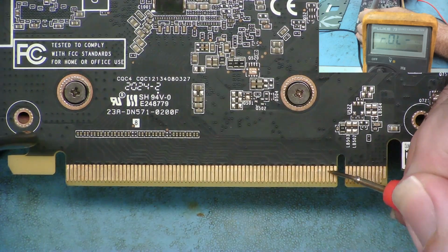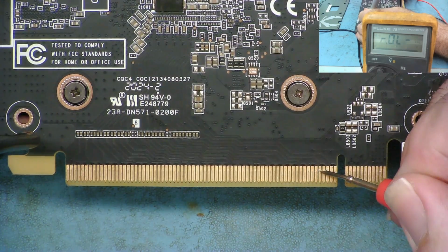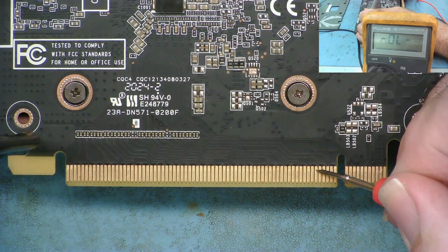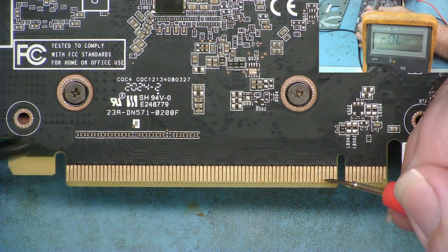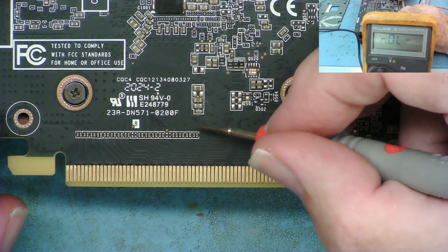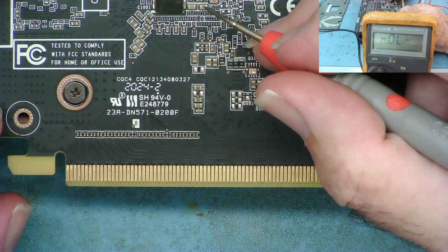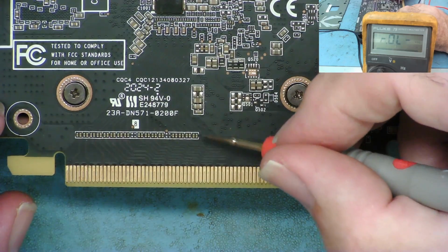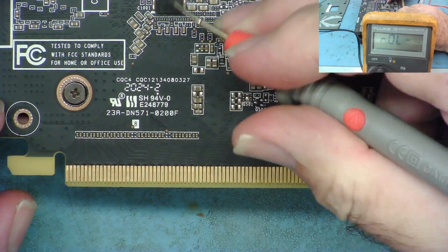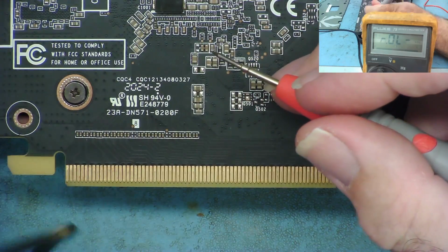So on this, again, we need to have a look. So you've got 1, 2, 3, 4, 5. Now that reads open circuit, and pin 6 reads open circuit. And this is actually okay, and the reason it's okay is because these tracks go to all these capacitors, so I need to test from the other side of the capacitor. Because of the capacitor isolating these pins from any voltage on here, there shouldn't actually be a problem on these ones.